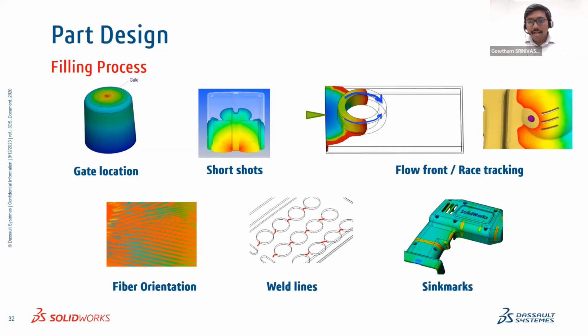We can find in detail where the weld line is, and we can change the gate locations to transfer the weld lines from the critical load acting zones to the non-load regions. And we can plan the thickness profiles based on the thickness distribution. As a plastic part designer, we can build our plastic part in a more confident way. By that, you don't need to go through multiple iterations. You will have a better idea of how manufacturable your plastic part is, and within a first iteration you can give better results.